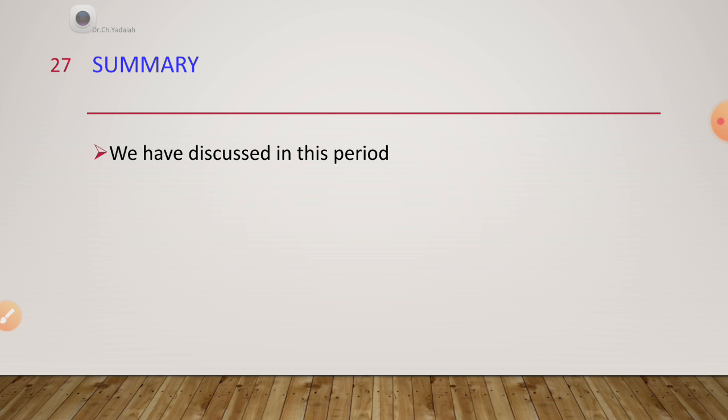Okay. So what have we seen in this class? The performance of the synchronous motor with excitation: normal excitation, under excitation, over excitation. At that condition, what is the back EMF developed? What is the load angle? We have seen that. And at the same time, we have seen the power flow diagram from stator input to rotor output and how these changes take place.